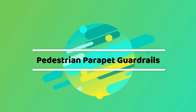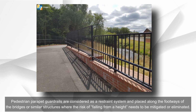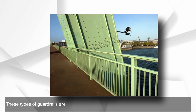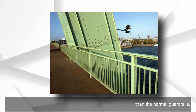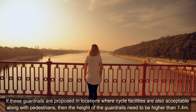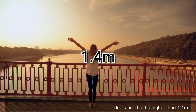Pedestrian parapet guardrails. Pedestrian parapet guardrails are considered as a restraint system and placed along the footways of the bridges or similar structures where the risk of falling from a height needs to be mitigated or eliminated. These types of guardrails are made of heavy-duty specification than the normal guardrails. If these guardrails are proposed in locations where cycle facilities are also acceptable along with pedestrians, then the height of the guardrails need to be higher than 1.4 meters.